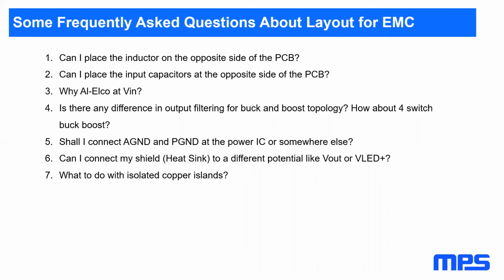Question number 2, can I place the input capacitor on the opposite side of the PCB with respect to my IC? This is a clear no. The most important thing is input capacitors directly at the IC. So this would be a no-go.